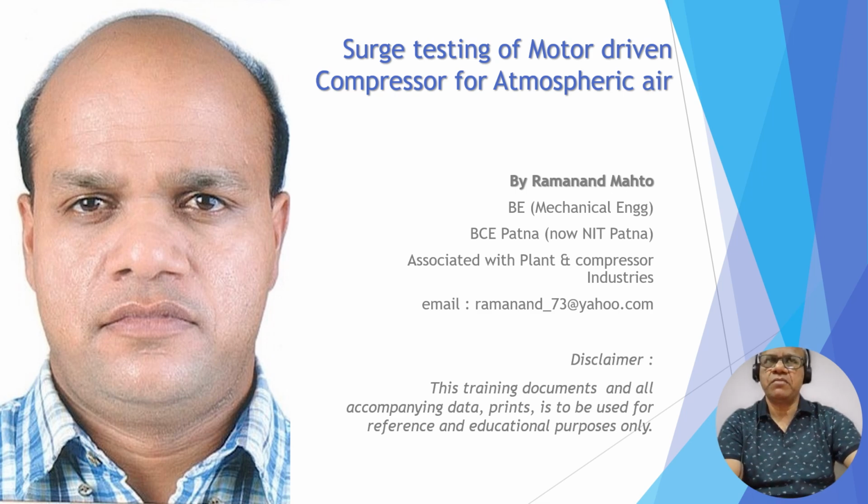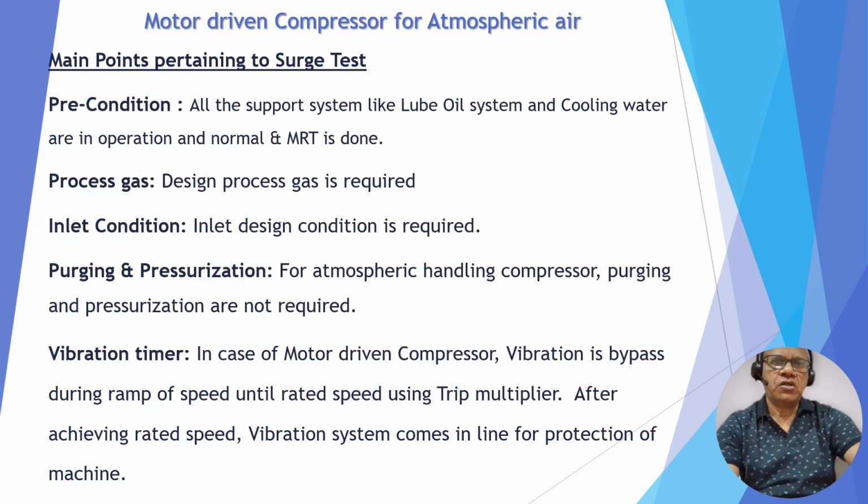A compressor is driven by a motor or a steam turbine. Sometimes a process turbine is also used as a backup or support. So these are the main points pertaining to the surge test. Precondition: all the support systems like lube oil system and cooling water system shall be in operation and working well. The MRT, that is the mechanical run test of this compressor, is already completed.